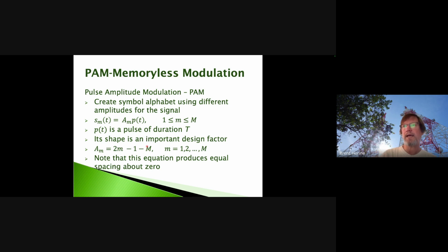So let's say k is 4, right? So 2 to the 4th would be 16. So we'll map in 4 bits to a symbol. So we need 16 different symbols. Am I saying that right? Let me make sure. Yeah. So cap M is equal to 16.